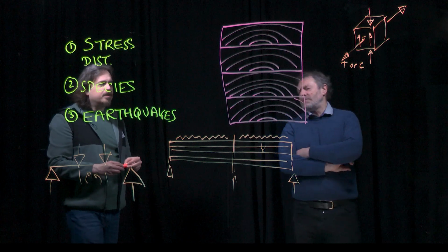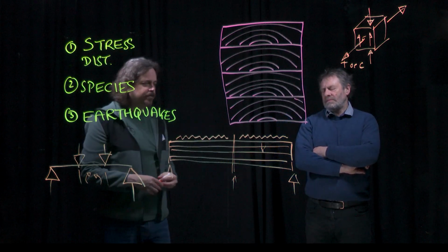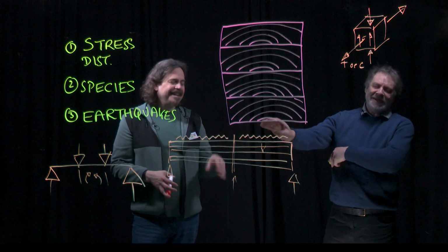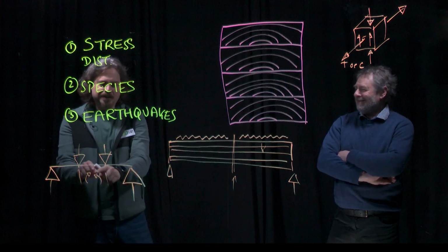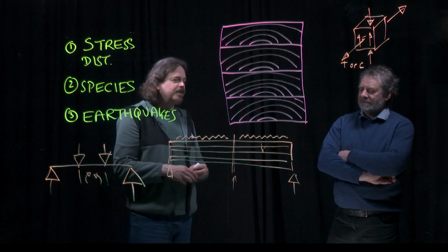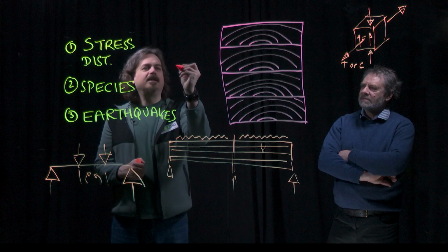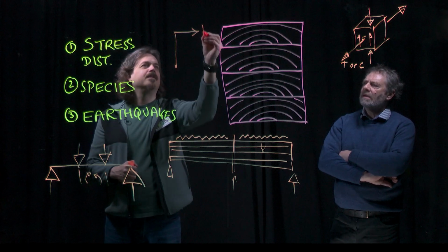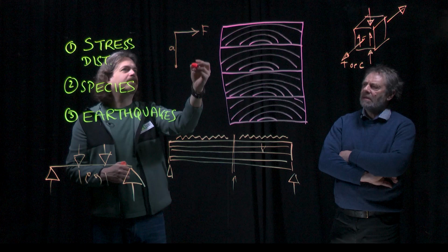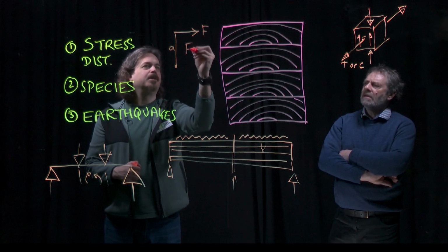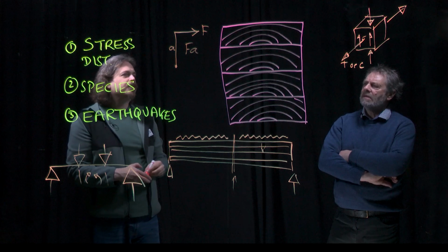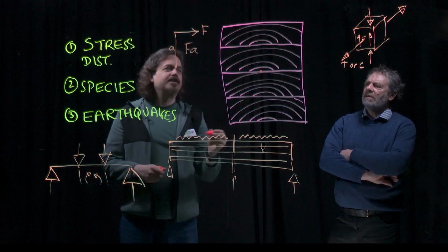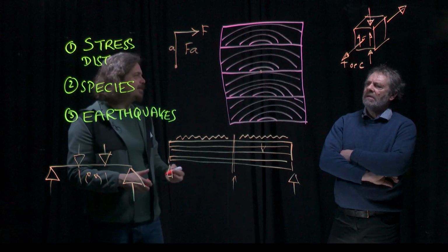So what we're trying to balance in our free body diagram, which is the element cut out, are just these turning forces. If you have a force acting at a distance from a point and something is rotating about that point, you can calculate the moment. It's the turning action of that force, the force times the distance. So for the forces, the turning point turns out to be in the middle of the beam.